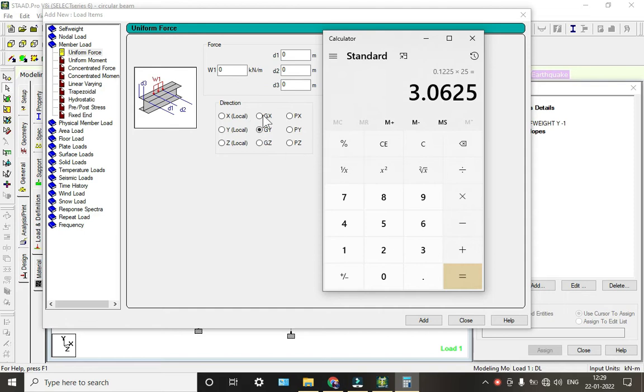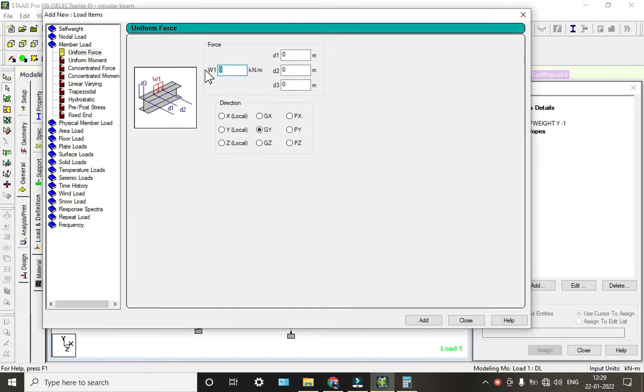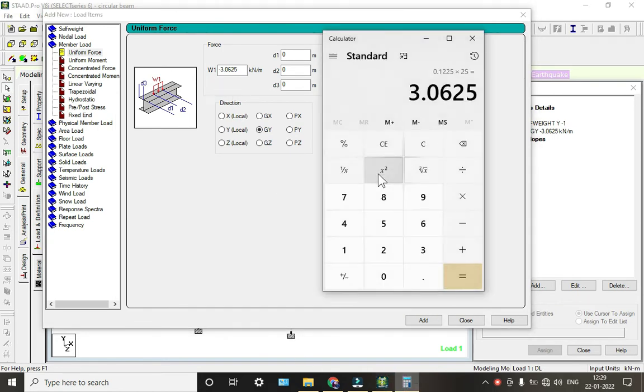or you can go to top view and select. Here you can see which beams are selected or not. So I have selected all these beams. So we will add this: assign to selected beams, assign and save.